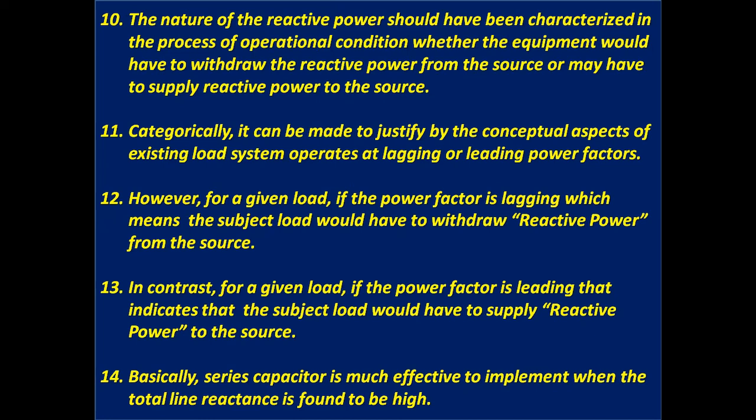Categorically, it can be justified by the concept of whether the existing load system operates at lagging or leading power factors. For a given load, if the power factor is lagging, the load withdraws reactive power from the source. In contrast, if the power factor is leading, the load supplies reactive power to the source.